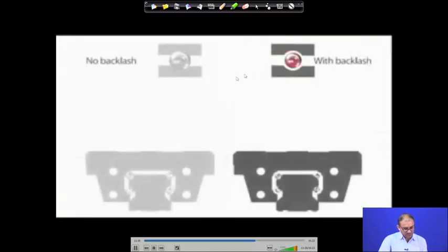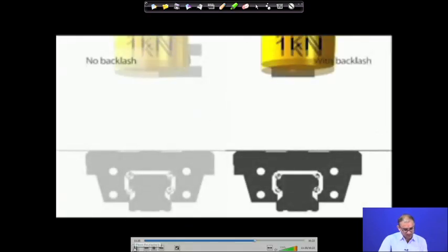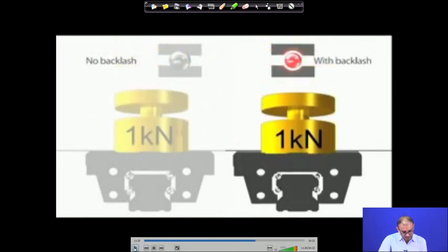Now this is considered backlash. Under backlash, what is going to happen is that when you add a 1 kg load, your whole thing will go down. Your reference surface is shifted a little bit down. So now your whole machining goes the wrong way because of this. Consider again the same example: you want to cut a slot, and you consider this particular depth to be 50 micron.